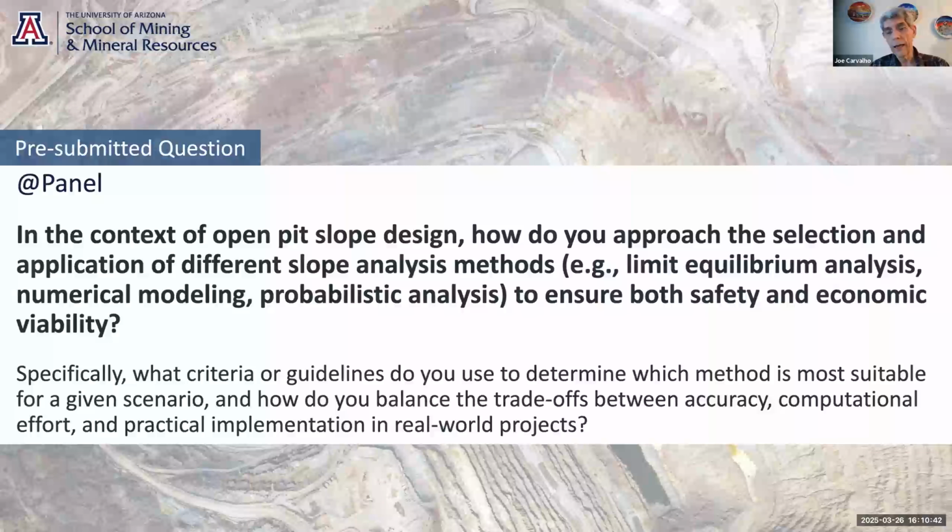And then you can move on to numerical modeling. One of the things that we usually do to confirm the results from limit equilibrium is that the numerical modeling is going to give you a more accurate or true failure surface, which you might miss in the limit equilibrium depending on the search method. So it's always a good way to check back on that.